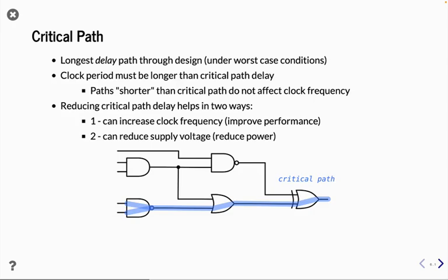And so you often really want to optimize the critical paths, whether it be for power, performance, or both. You really want to get a handle on this. Like I said, in this example I just gave, in the same technology family, changing the voltage is going to change the delay in terms of picoseconds or nanoseconds. You're not going to change the FO4, because FO4 is relative to inverters, right? So if you lower your voltage, it's also lower for the inverters used for the same comparison point. And so to improve your critical path, you're going to have to improve your FO4.